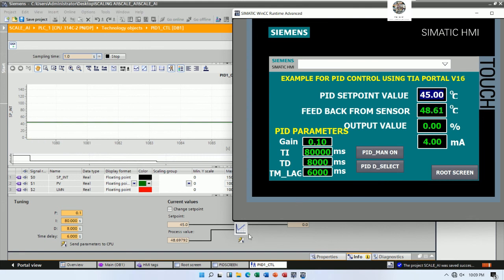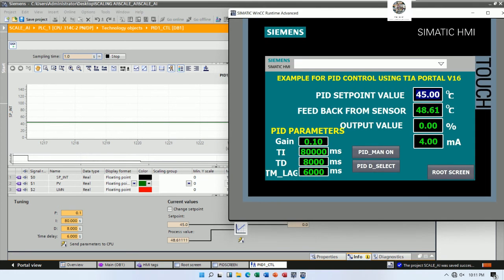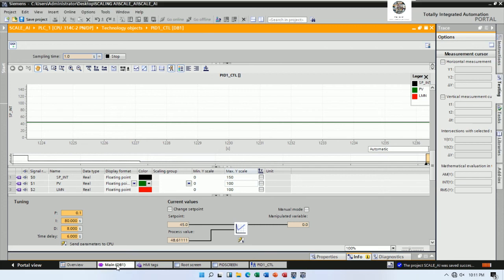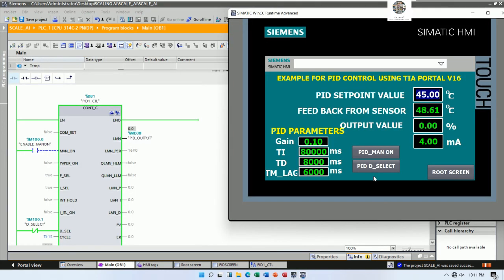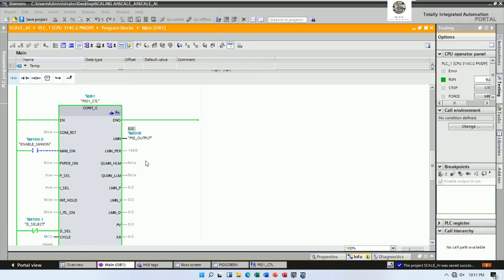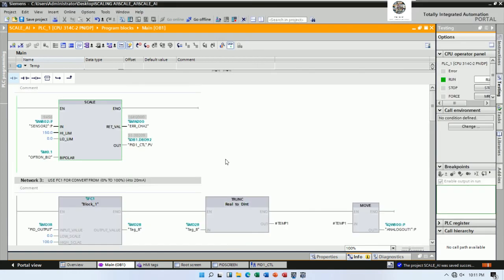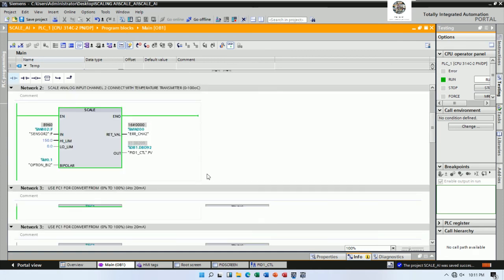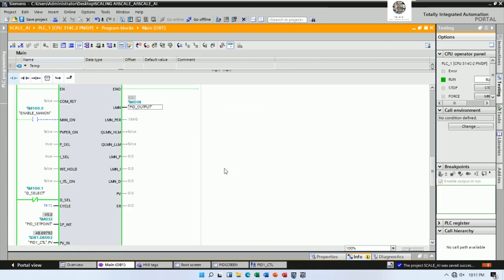And I will change the address of this one a little bit. So we can see and monitor and control the PIDs that we want. So this is just an example. I will change the address of this one a little bit because we cannot control right now. When I push here, it does not work, right? Because M100 we already use here. So we cannot control.